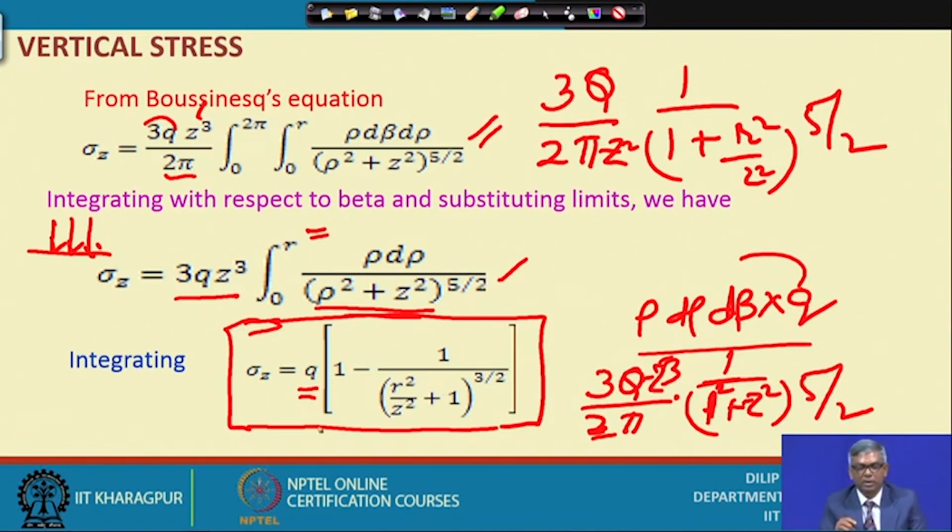So far, by this integration, what I have got is this: when a load is applied through a circular footing, along the central line of the footing, vertically below the footing, this expression gives you the stress intensity, but not at any other point. At any other point the intensity will obviously be less, and we can also find it out, but there is some complication in the method. So I am not discussing that right now; later on we will discuss it.